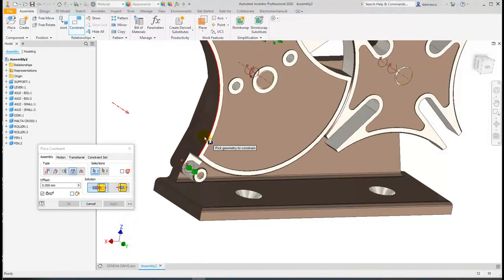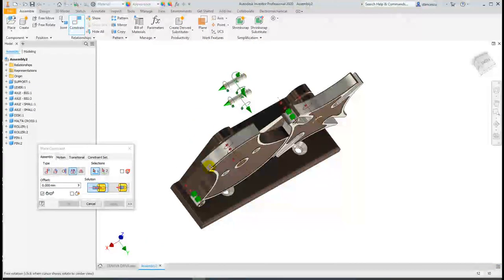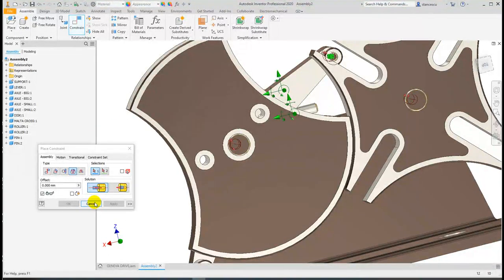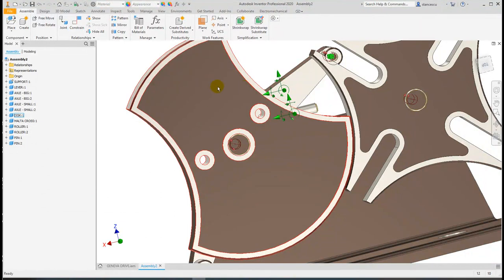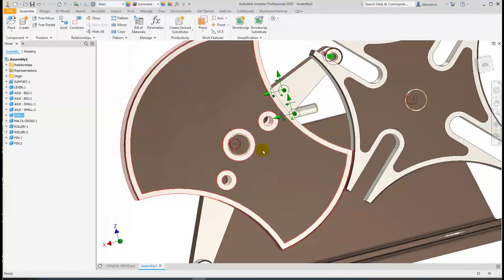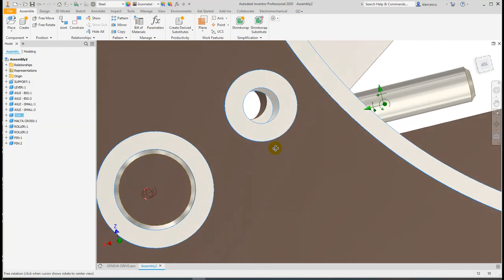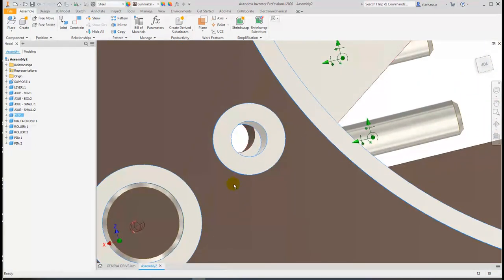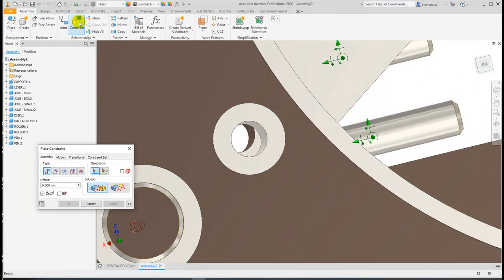Apply. Very interesting. And now the last elements, but before I rotate this disc to be somehow aligned with the two holes here. Why? Because I constrain now mate, mate, mate, mate, and choose this axis and this axis to put them together.